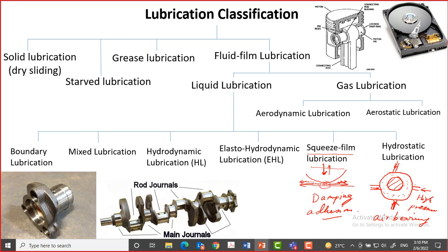Excuse me, sir. Yes. Sir, you are saying that squeeze film lubrication is like, in every surface there are irregularities in surfaces. Yes. So lubricant is also present there, which helps to prevent adhesion bonds between the surfaces. Yes. So in general, we can say that every lubrication has a squeeze film lubrication. Not every lubricant will have sufficient for our engineering system.